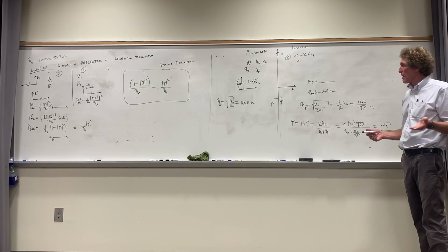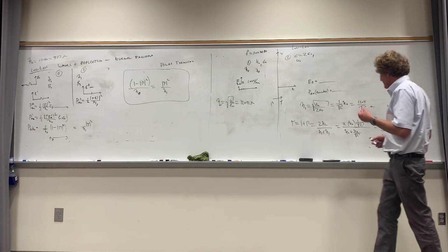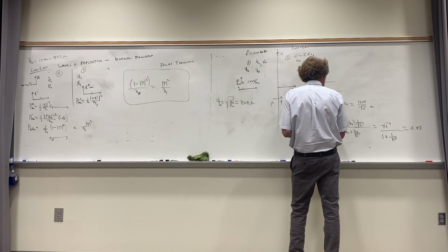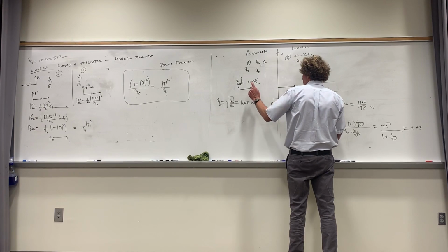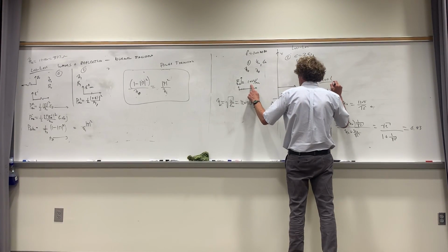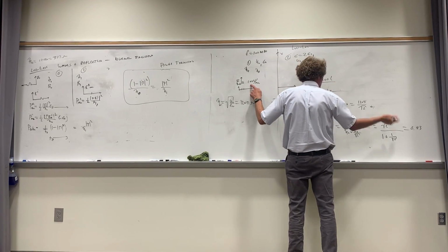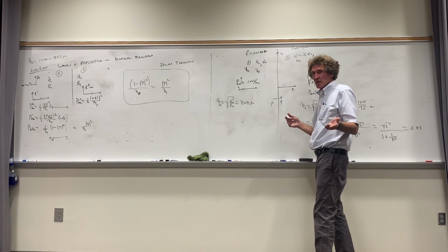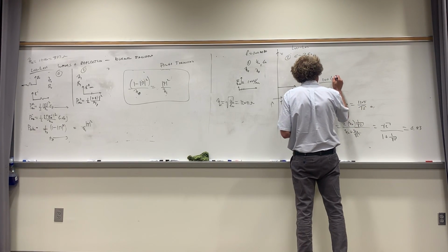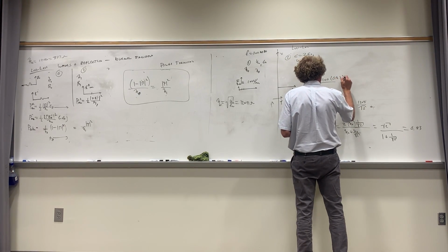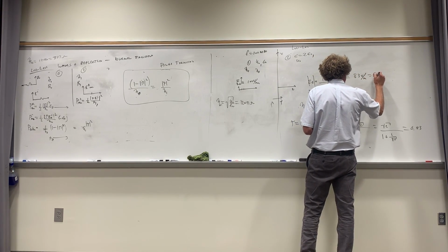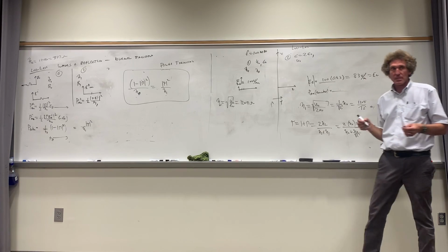I have that. Now I wanted the electric field transmitted, its magnitude only. I don't care about the phase usually. So the magnitude would be what? The incident electric field, 100, times what? Come on. Transmission coefficient, right? We just calculated. 100 times 0.83, or it would be 83 volts per meter would be the electric field transmitted. Do you all agree with me, class?